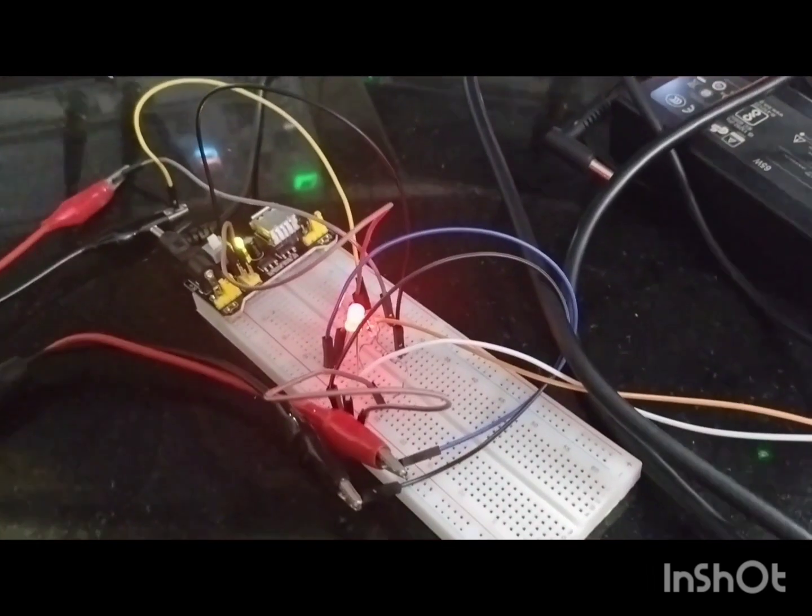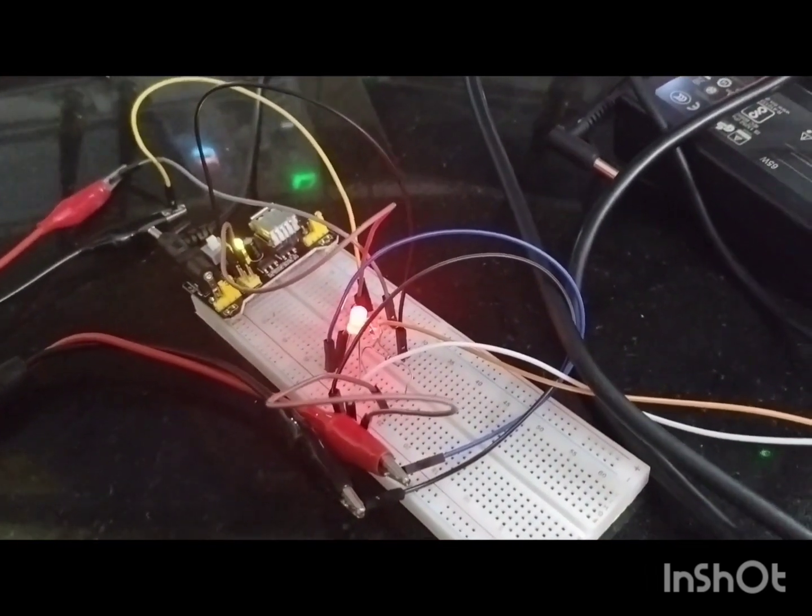When we come to the measurement setup, we connect a 330 ohm resistor to the LED and a 10 kilo ohm load resistor to the photodiode, as seen in the circuit. Channel 1 of the oscilloscope measures the input waveform across the 330 ohm resistor. Channel 2 captures the output voltage across the 10 kilo ohm load resistor. I am going to explain the connection circuit for task 2.